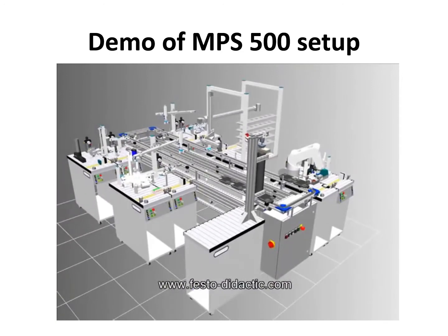The conveyor itself also has a controller, and the controller of the conveyor is located here on this box. This box also is equipped with the start, stop, and some indicators and LEDs. All of these switches are inputs to the PLC. Sensor signals are input to the PLC.